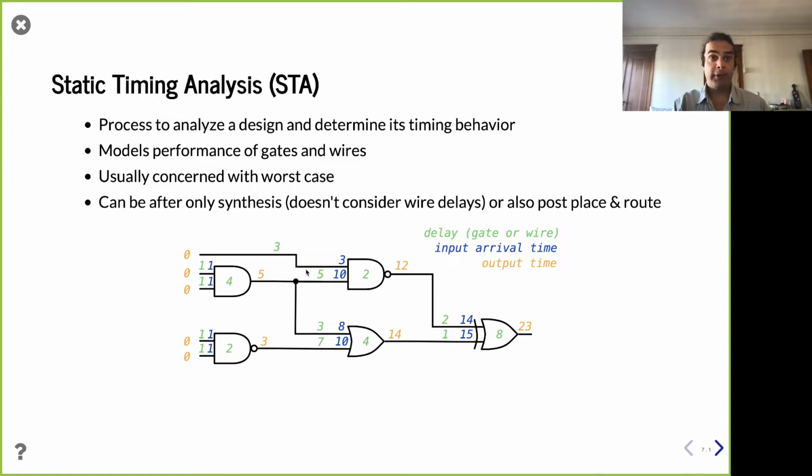It may or may not be placed and routed yet. And it has models, right? It knows for the gate how long to take. Okay, the gate takes this long, or this wire takes this long. Or actually, in this technology, if you fan out by this much, it takes this much longer to charge that many endpoints. It has some sort of back and forth model for all the components. But even though the models for each individual component are simple, in aggregate it's trying to put a model together for your entire system, right?